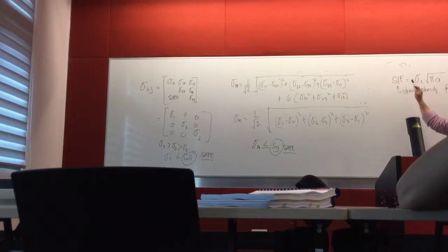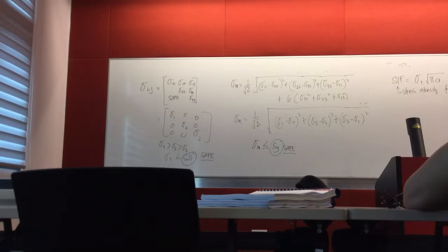You already have this one here from that. So once you have this one, you always have that crack. What's the assumption here? The assumption is that your material will have a crack. Your material is not perfect, so it will contain a crack. Even if it contains a crack, there should be a certain length wherein that crack will not grow. We allow the presence of crack because our material is not perfect, but up to what size of crack do we want it to be? That's the A, half length of the crack. These are the things that you wanted to know.